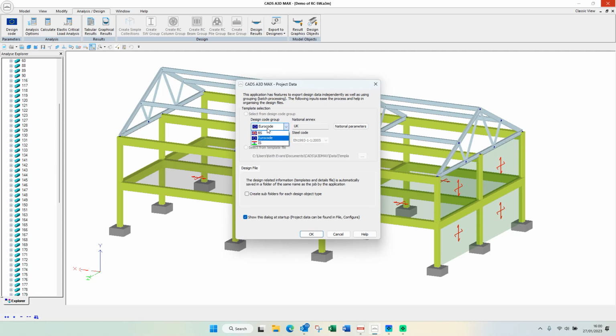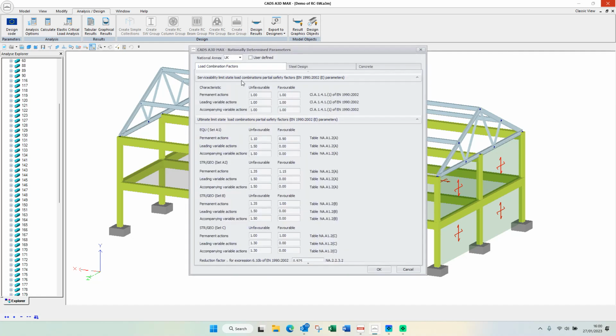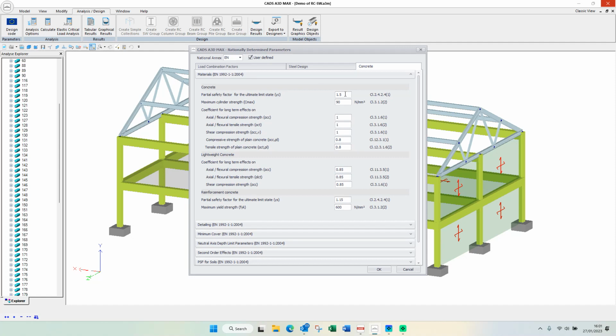Now this is where we've actually tried to help with Eurocode and all the combinations that come in. British Standard, you put all the factors in yourself and the combinations. Eurocode, you can actually use a generator within the program, and this covers British Annex and Irish Annex and general EN, which you can then tailor to suit your own particular region. All these values can be edited if you put the user defined on.